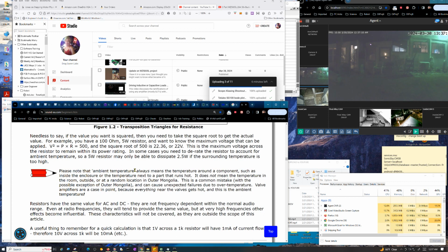And that's the big question, how close, because you do get radiative emissions, especially from real hot components. But you're mostly interested in the temperature of the air. I would say maybe a quarter of an inch or so below the component. Ten millimeters or 5 millimeters might be getting a little close. But what you're really interested in is the temperature of the air that's being drawn into the convection plume of the component.